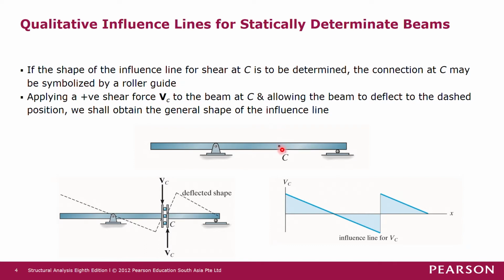So if we want to look at the shear at C, then we cut across C and place a roller guide over there, and then we apply the positive shear forces at the respective location of the roller guide. So please remember that we are using the positive shear direction as this. This is the positive shear force direction that we use.